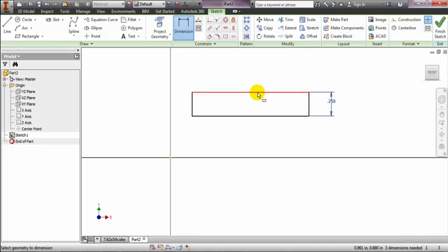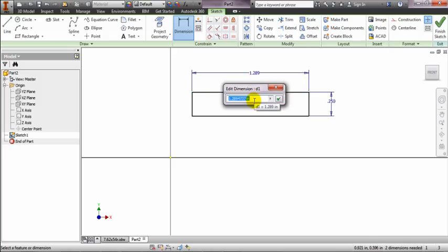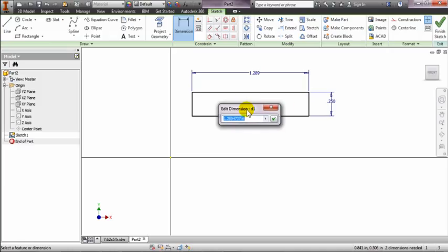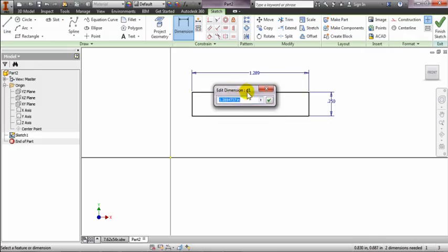I am now going to create the length of this drawing, and for my length I'm actually going to use my original dimension over here to create an equation that's going to make this line a specific length. Right now my length is 1.289 and so on, and yours is going to be something different because we drew this freehand. But notice that it says edit dimension D1. This is my dimension that is labeled dimension 1 or D1. This dimension is D0. It's the first dimension that we ever created. So this is going to be the dimension that everything is based upon.